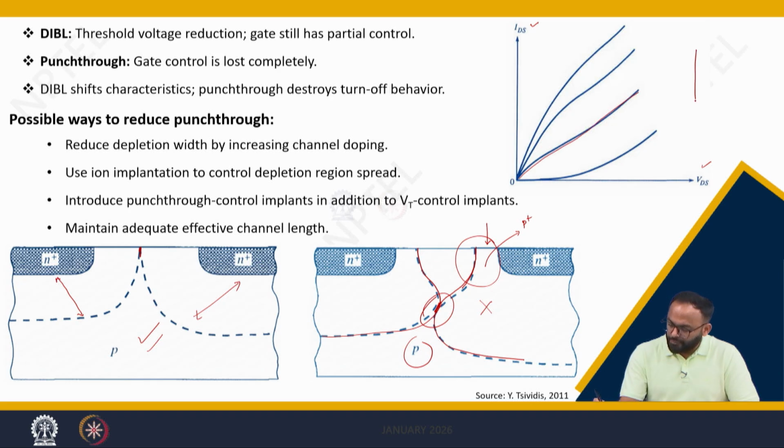Why? Because if you remember, the plot of ID versus VDS shows a nice transition from non-saturation to saturation. If you do not consider the velocity saturation, you will get a more abrupt transition, right. However, the ID-VD characteristic because of punch through shows an abnormal behavior where the current is rising and not saturating, correct.